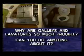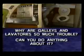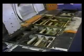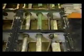What causes laboratories and galleys to be such corrosion trouble spots, and can you do anything about it? Spills and leaks in galleys and laboratories, particularly the deck under laboratories, sinks, and ranges, are what makes these areas so troublesome. You can't be there on every flight to prevent every spill, but you can pay special attention to these areas during routine maintenance. Clean them frequently in order to maintain their protective sealants and paint finishes.